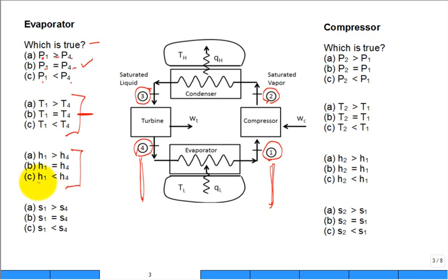C. So, all right, we're going to switch to A. So the enthalpy at 1 is higher than the enthalpy at 4. That's your answer? Correct. Think about energy. As energy is transferred in, which it is, into the evaporator from the surroundings, it's evaporating the fluid and the energy content of the fluid is higher on the outlet and it's going to be realized by a higher enthalpy. You're done too. Entropy. Yes, sir. S1 is greater than S4. So this is A. Right.